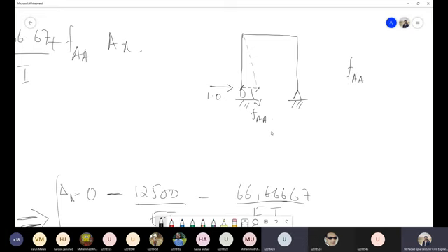Yes, so in that case, what will be our equation? That will be again integral 0 to L, capital M, small m, over EI, dx, right? So what is this M? Can anyone tell me how we will write the equation of this capital M for this particular case? Small m squared over EI. So okay, we will go by the procedure. Now the first step is, this is our initial structure in which the unit load is acting. So we have to write the equation.